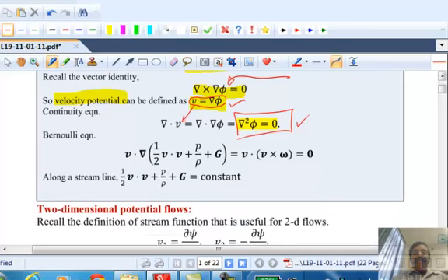And we saw that if we take the Euler equation and dot it with the velocity vector, we dot a force term, that is your energy term or the work term. So that gives us the condition that because of the condition of irrotationality, this is equal to 0. So the meaning of v dot del is following the motion of a fluid particle in a Lagrangian frame. Whatever appears in this parenthesis is conserved because its gradient is 0. It doesn't change along that line.